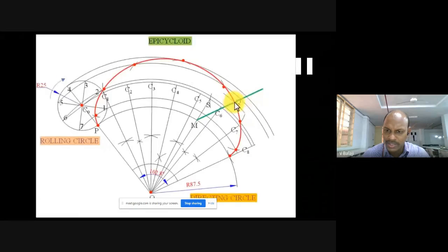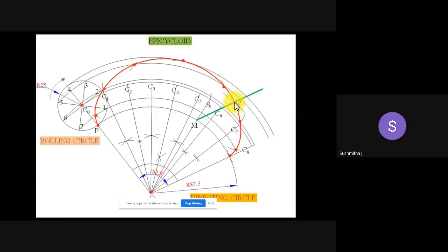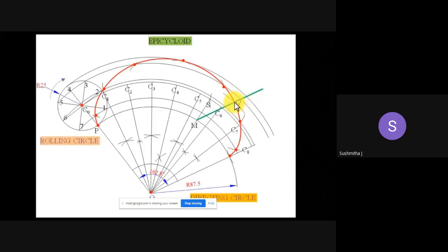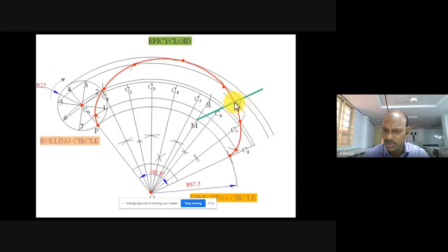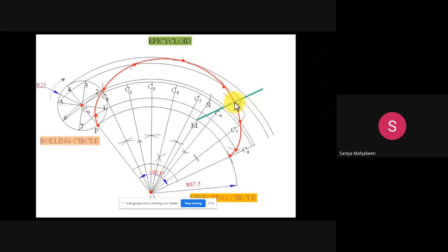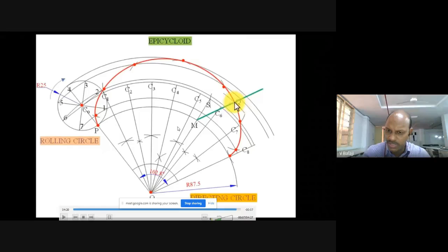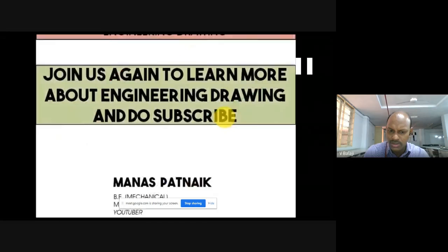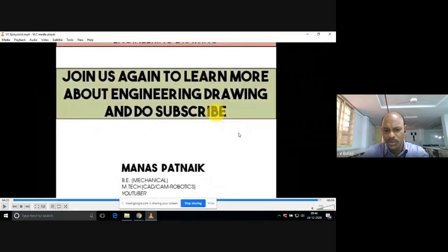And do you know how to get the tangent? Perpendicular to the normal. From where do we need to draw the perpendicular? From Q, Q only. With the help of a protractor or mini drafter? Mini drafter. Match one of the mini drafter scales to this green color line and tighten the mini drafter. Then move the mini drafter to point Q and draw one perpendicular at that point Q. In this way, you can make it up.